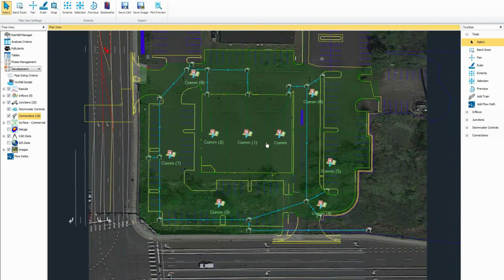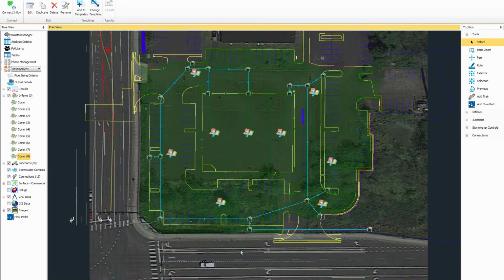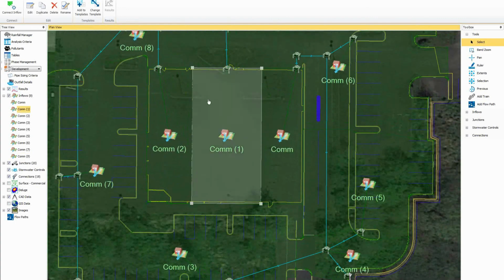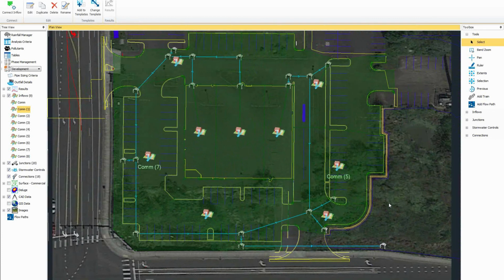and we'll see that sure enough, we have now not only brought in this pipe network, but also, since we have these junctions, this system that came in with our inflow areas, you'll see that all these inflow areas were really automatically associated. So I don't need to now manually associate these. It automatically found that, hey, this roof area, well, this all drains to this downspout, right? Here's this little lateral. So we automatically connected that, right? So it's pretty useful to get us moving ahead pretty quickly.